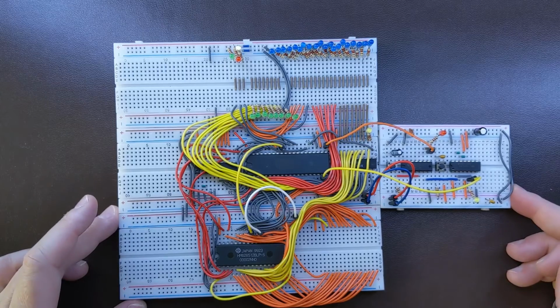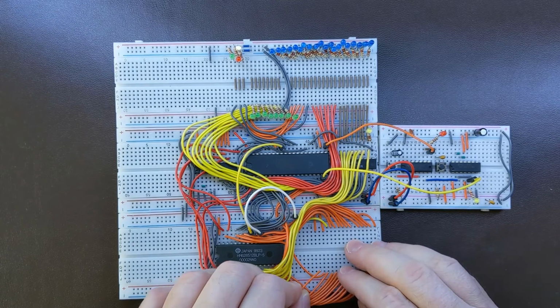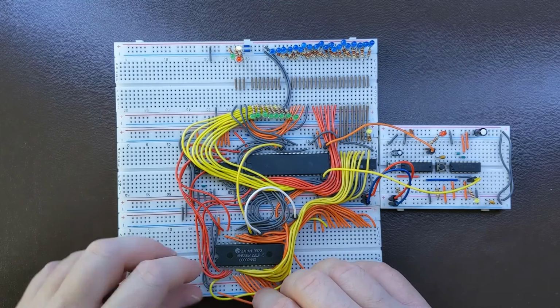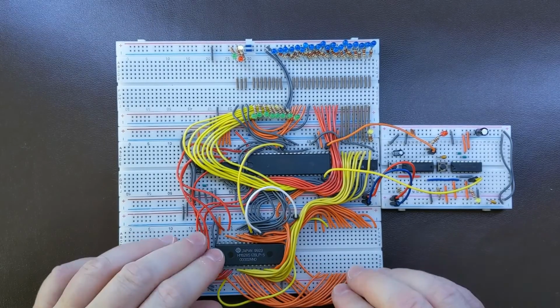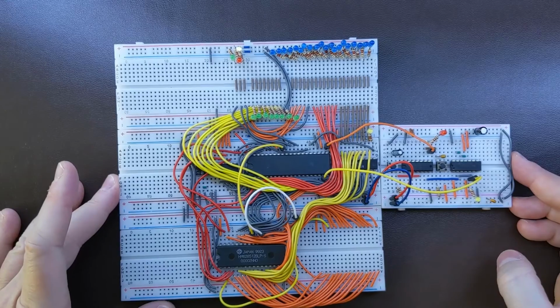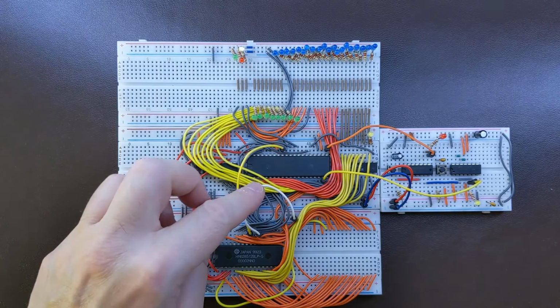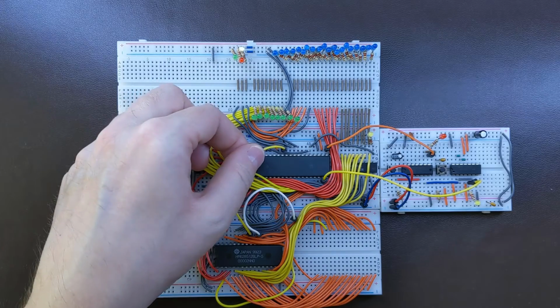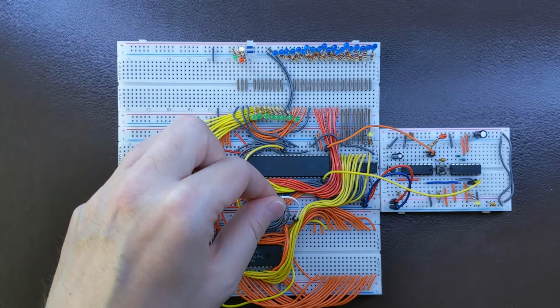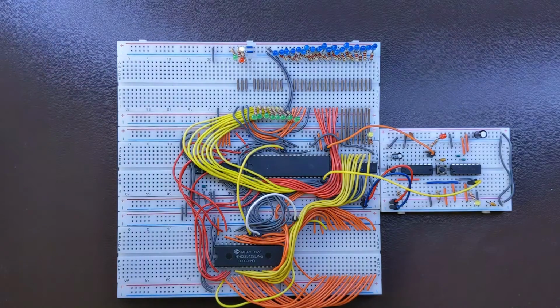The missing one is pin number 2, which is A16. A16, oh, that's pin number 2 in the RAM as well, so that is gonna be easy. Okay, looks quite okay. I think if we just returned the, oh, we've got a read signal from the CPU here, and that is output or chip enable, which is now shorted to the ground.